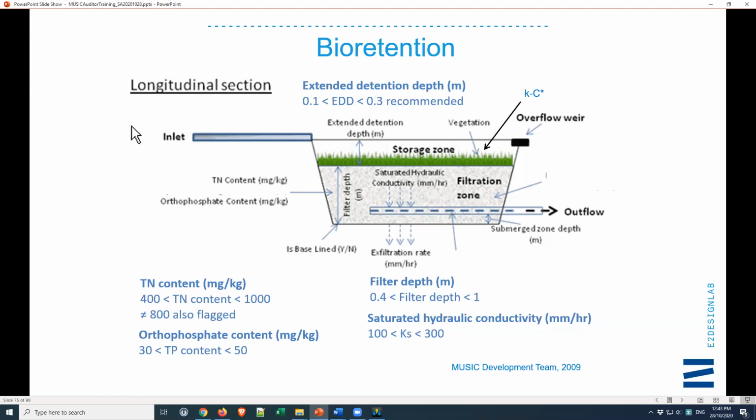the plants. Now that can either be a gravel or a sand storage above a slow draining underlying soil like clay, in which case you might not bother lining it, because if the water goes anywhere, it's not going to go far. The plants will find it if it's in the clay around it. So I wouldn't have an issue with a submerged zone with no lining if it's in those kinds of soils. If it's in sandy soils and you want a submerged zone to effectively hold water for the plants, then obviously you need to have a lining in it.